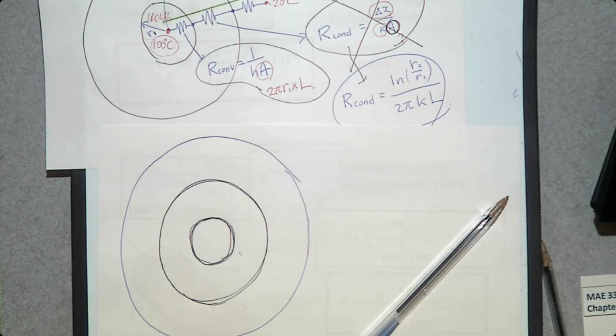Kind of. So when you bury the pipe underground, that means you are going to rely on what kind of heat transfer? Conduction, because the soil is not moving, right? But if you place them in the air, it's going to be convection. So conduction is much slower than convection, right?